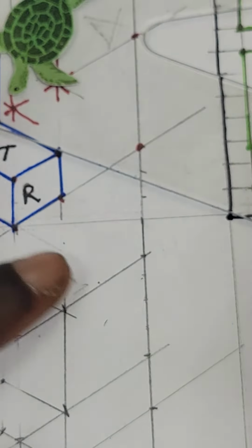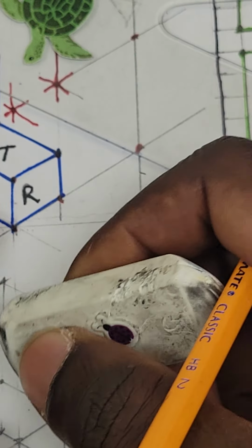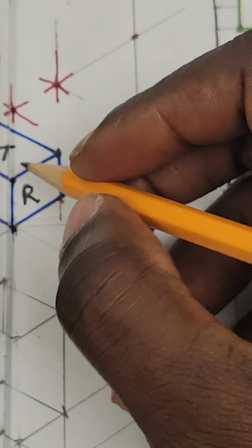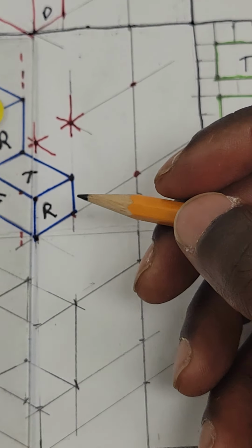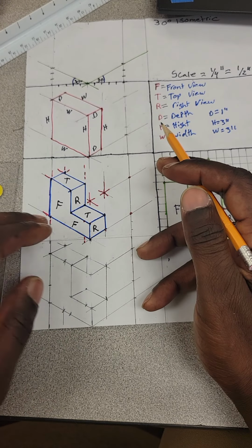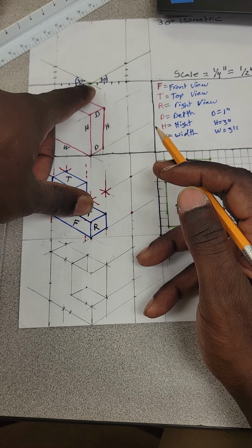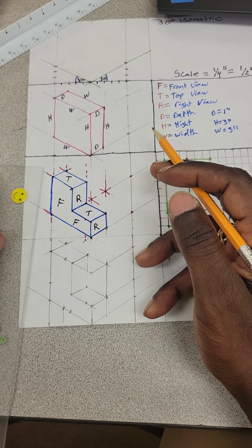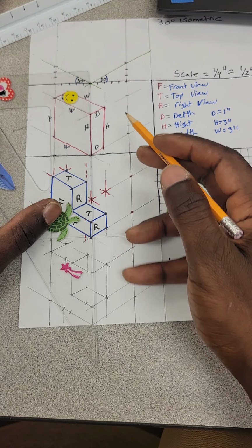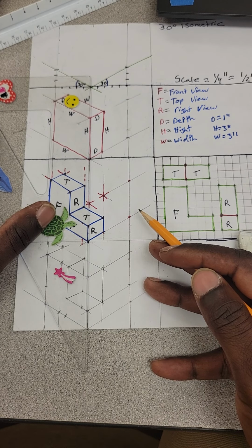But this is also another thing too, when you're building homes, right? A lot of folks wonder how all these windows and doors line up. It's called transferring the line down, right? So we literally went like this. Let me zoom up. We literally took every line and stacked down. This is just like laying out a building. If you're laying out windows and doors, you create a benchmark, your starting point. I literally took my ruler or my level, and I leveled down from each point. I can do that, and I should be lined up all the way down, straight line.